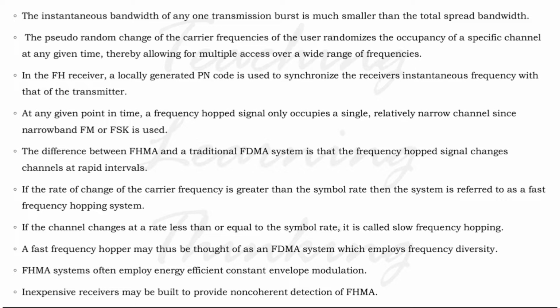The instantaneous bandwidth of any one transmission burst is much smaller than the total spread bandwidth. The pseudo-random change of the carrier frequency of the user randomizes the occupancy of a specific channel at any given time, thereby allowing for multiple access over a wide range of frequencies.